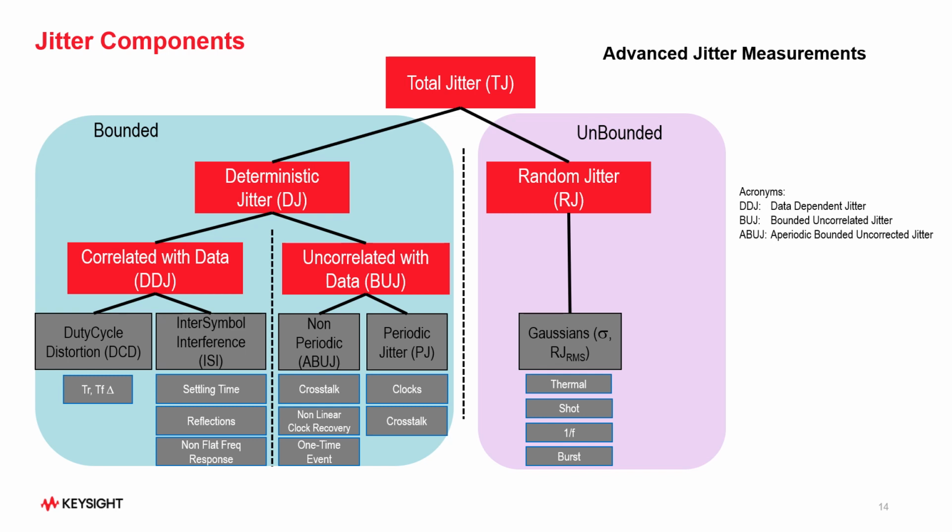The next thing we would like to deliberate is the jitter components, like I mentioned earlier. Why is it important for us to separate the jitter for analysis? The main reason for having all the different jitter components separated is that one can figure out where the source of the problem is coming from. Let's look at what the jitter components are made out of.